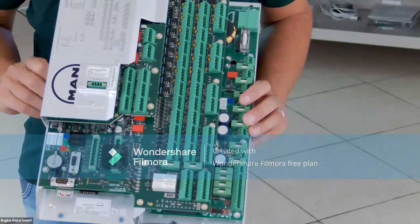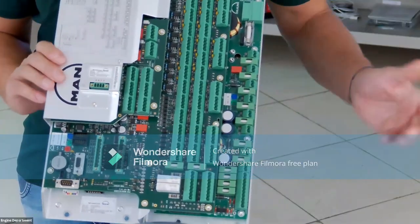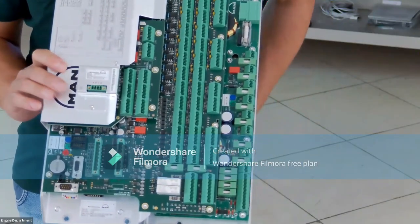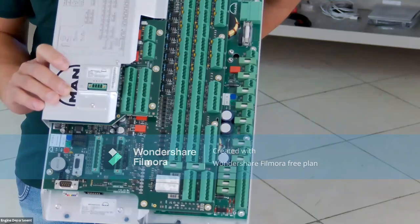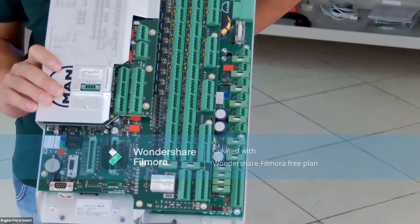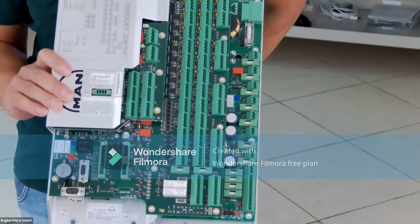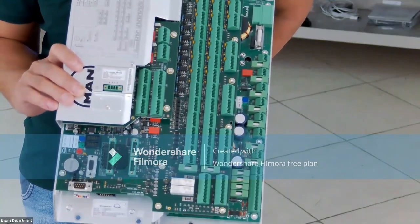Is it only necessary to just push the reset button then? Yes. Sometimes if it gets frozen, it depends on the controller. If the controller type is ECU, engine control unit, or engine interface control unit, where the controllers are duplicated, you can press the reset button also when the engine is at full speed.